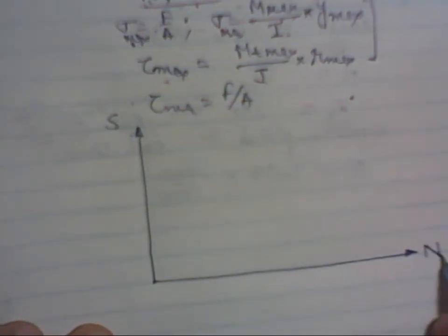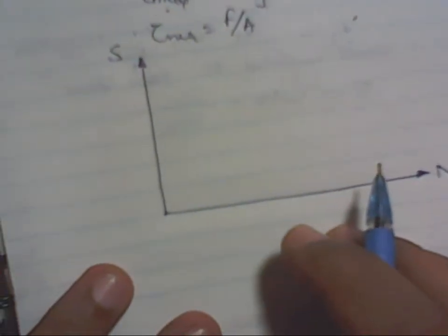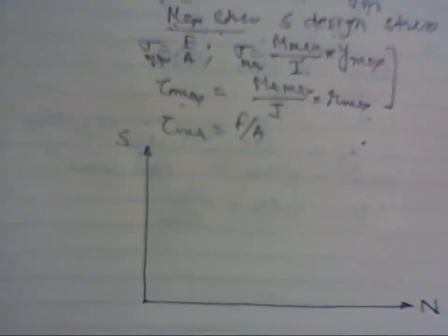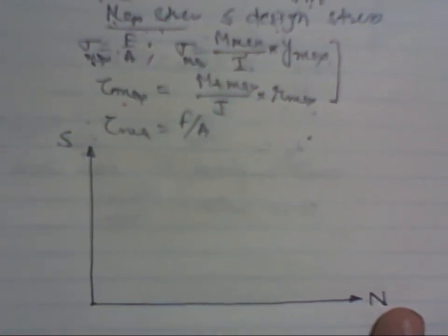We conduct that test on a standard fatigue machine and plot the curve between stress and number of cycles. We conduct the experiment by loading a standard specimen and then rotating that specimen under load so that it is under variable or fluctuating stress for bending load.